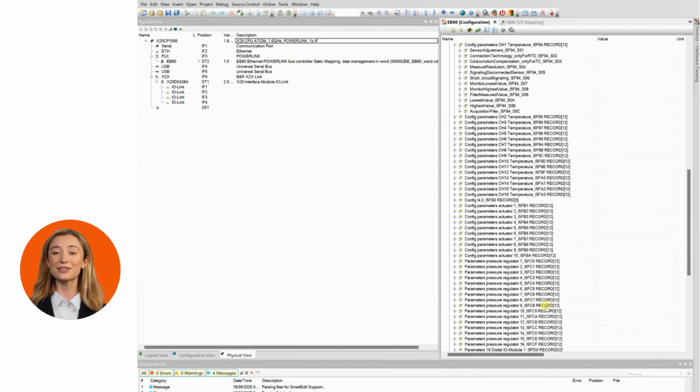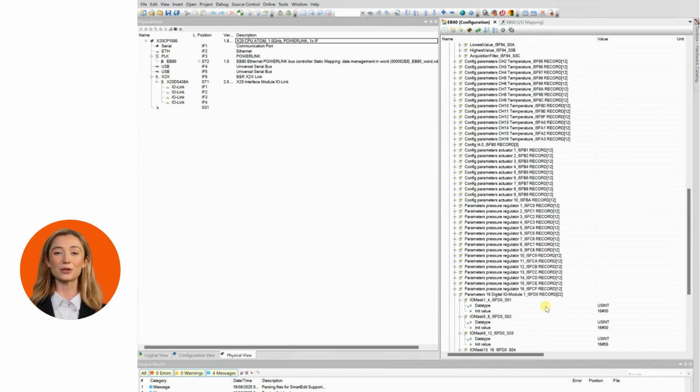Configuration of the parameters of the module with 16 configurable digital inputs and outputs. Each module has 16 channels that can be individually configured as digital inputs or digital outputs. The polarity is PNP. In addition, inputs 1, 2, 3, and 4 can be configured as channels for reading encoders with a maximum frequency of 300 Hz, such as DC motor encoders.